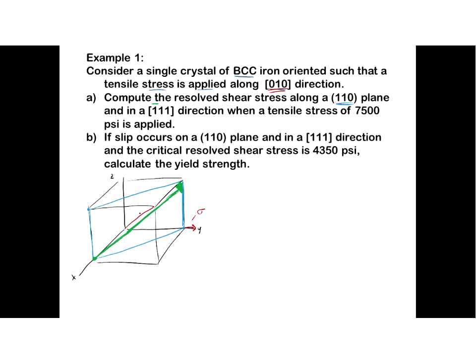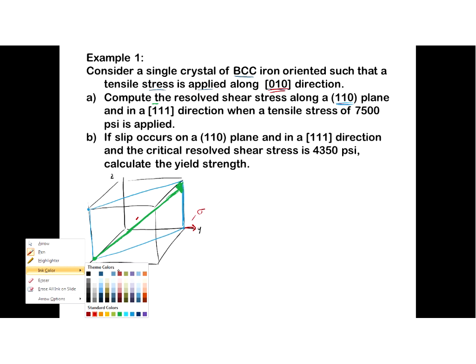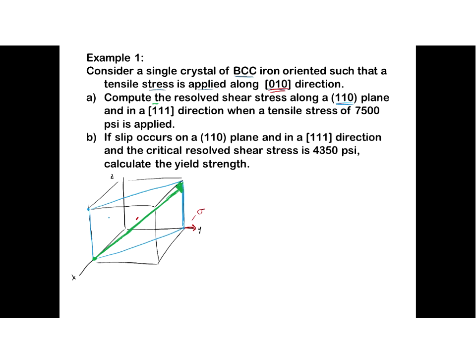It would be if I drew a different plane of the 110 family of planes. But I drew the 110 plane as I see it here, just as the exact 110 plane, not from the family. If I drew the family that goes from the back z-axis over to this side, then that'd be okay. But we know we're not using a direction that is not within the plane. Okay, so I had a typo in my example.